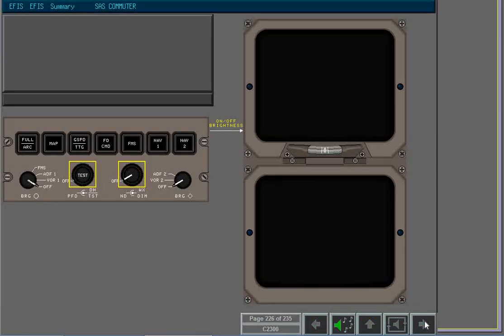The Fokker 50 is equipped with 2 electronic flight instrument systems. Display for each system is controlled from the on-side EFIS control panel. Each control panel incorporates on-off and brightness selectors, display mode selectors, display options, and source selectors.